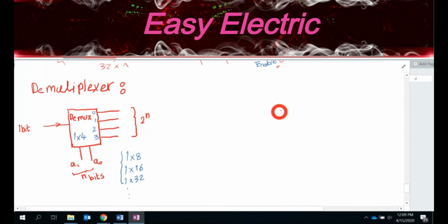So how could you make that? For making this unit based on the basic gates that you have, this is what's inside the box. So you just have 4 AND gates. So these are the AND gates. And each of them is your output. Okay, so these are the 4 outputs that you have. So I give 0, 1, 2, 3 as the numbers of the outputs.